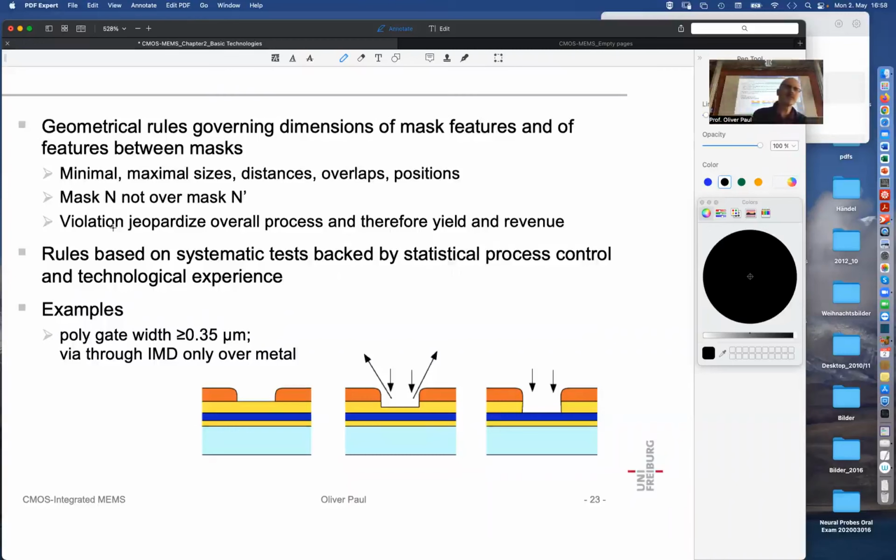In other cases, you may say, is it really necessary? And you pick up the phone and talk to the technologist, saying, for my microsystem, can I remove the dummy metal? It's disturbing because it conducts thermally, and we would like to make a thermal sensor. And he says, yeah, well, we can do that. It won't disturb the rest, but maybe your metallization in your structure won't be produced safely, at your own risk.